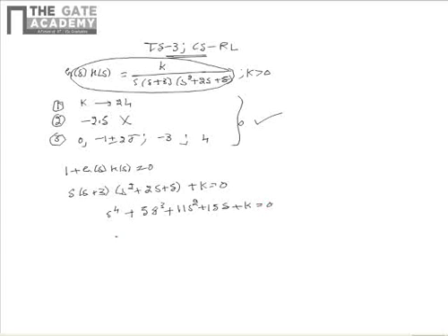The value of k for which the root locus intersects with the imaginary axis can be obtained by Routh-Hurwitz analysis, for which the Routh array is formed as shown. The Routh array's elements in the first two rows are written as 1, 5, 11, 15, k.